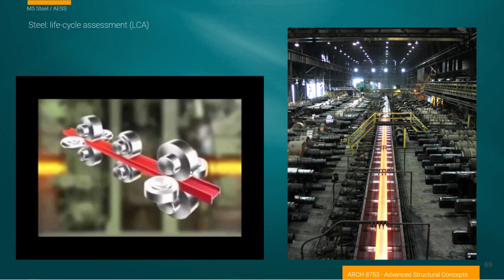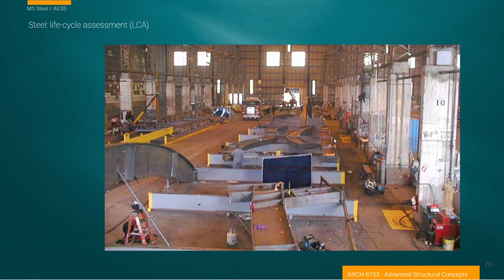So this is a rolling mill. Hot ingots come through, and they get rolled out through dies in order to create the flange depth and the flange height for us. And this is a look through a factory. On both sides of this, we're seeing a rolling mill, and the product is coming off of this rolling mill and being straightened out. It looks like they have spray to quench this, to cool it down as it's moving through the process. And over here we have all of the dies that are used to create all of the different shapes of I sections, C sections, or whatever in a steel mill. I thought it'd just be interesting for you to have a feeling for how these parts are created.